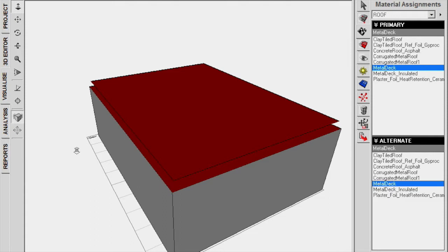So, as we think about roofs and the amount of solar radiation they actually absorb, what are the factors that affect how much solar radiation you absorb? Like, what do you think affects how much solar radiation actually gets through a surface? Like, of all the different properties. Is it the texture? What's that? Reflectivity. Reflectivity is a big one. Yes. And reflectivity is probably the best way to say it in terms of what's going on. Another way that's kind of simple to say is just in terms of the color. But reflectivity is truly the issue, because if you have a surface which reflects an awful lot, then the radiation won't get absorbed. If it doesn't reflect a lot, then a lot of radiation is going to get absorbed into it.